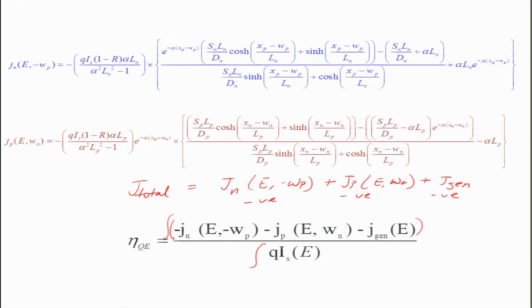and the total current which is obtained because of electron hole migration and generation current, so diffusion current plus generation current, should give you the ratio of this current with respect to whatever power is incident. So basically this is the spectral flux or spectral energy. If you multiply this by charge, you will get that many carriers that should be created. So the ratio of these two will give you the quantum efficiency of the device.